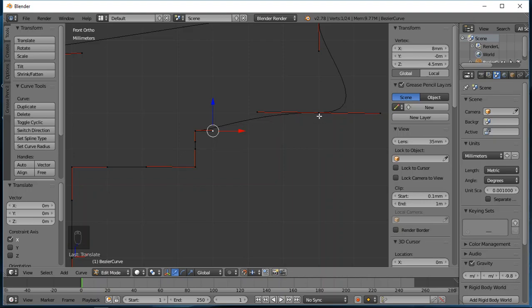So actually, that's fine. This one I want straight up at 11. So the X coordinate being 11, and the Z just a little bit higher than it is, so maybe 5.5. So it gives it a nice square corner. Although that's not as necessary because that's not touching anything. But I don't want it going past the 11, so it can pass through the hole in the fidget spinner. So that's probably an okay idea.